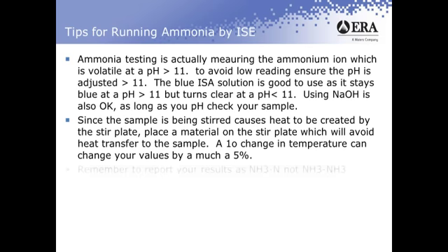Another important thing is to remember how to report your results. You're going to be reporting your results as ammonia as nitrogen and not ammonia as ammonia. So you need to make sure, if you're calibrating as ammonia, that you convert your results over to nitrogen and not ammonia. There's about an 18% difference or so in your values if you're not doing the conversion properly.